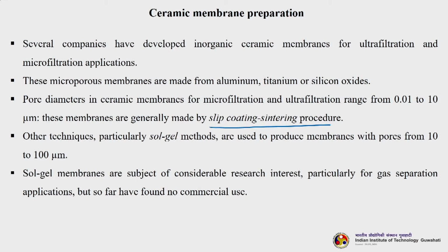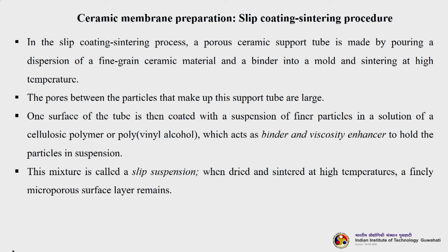Okay. So, other techniques, particularly the sol gel methods, are used to produce membranes with a pore size from 10 to 100 micron. Sol gel membranes are subject of considerable research interest, particularly for gas separation applications, but so far have found no commercial use. Now, let us understand what is the slip coating sintering procedure to prepare ceramic membranes.